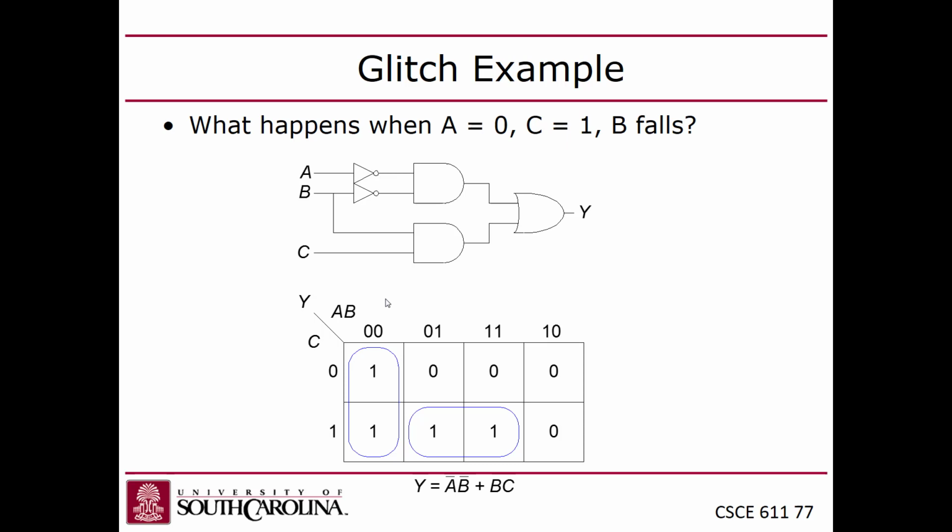So I'll change B, and the change in B will arrive at this input before it arrives at that input, because I have to go through a longer path if I go through this inverter. An update in B will go through this path, and it will go through this path, but it'll arrive on the bottom path first. You guys with me? So, what's the big deal?